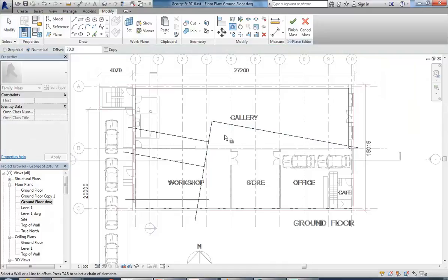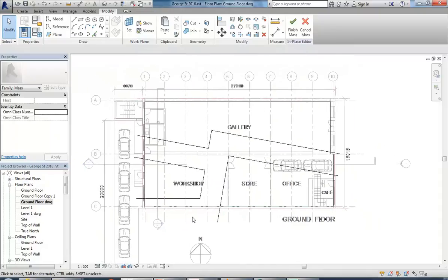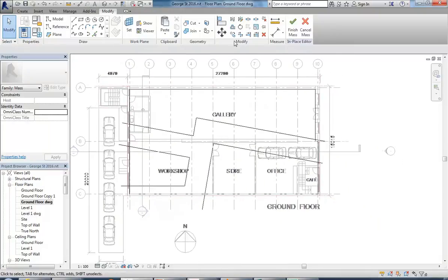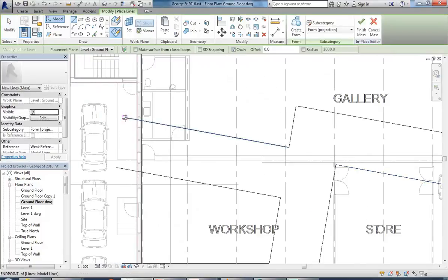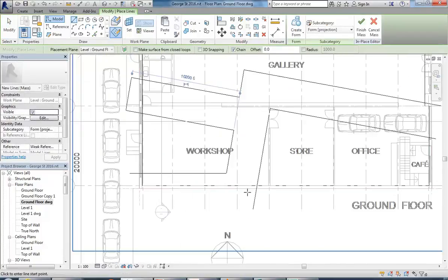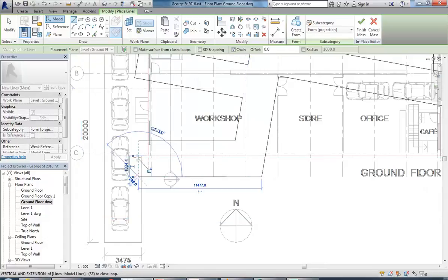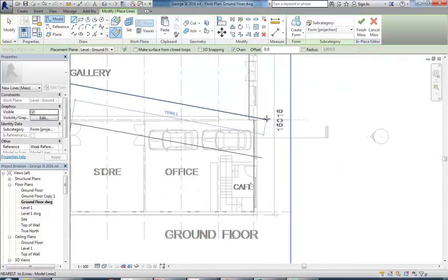So you've got all these standard drawing tools, hopefully you're used to using those. 3,000. Oops. The copy option needs to be turned on there if you don't want to lose the original lines. And then trim and all those other options work just like normal. Yep, there we are. Okay, so that's the basis for my void, and then I'm just going to join the ends using lines to make this into a closed shape. If it's not closed, it won't work properly.